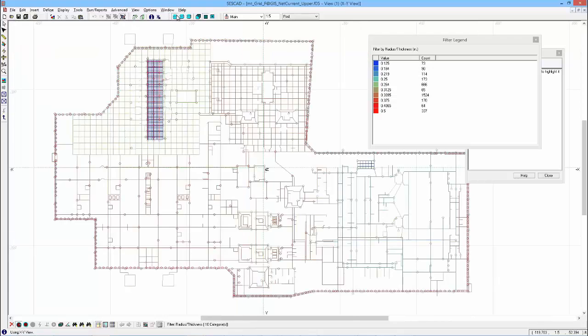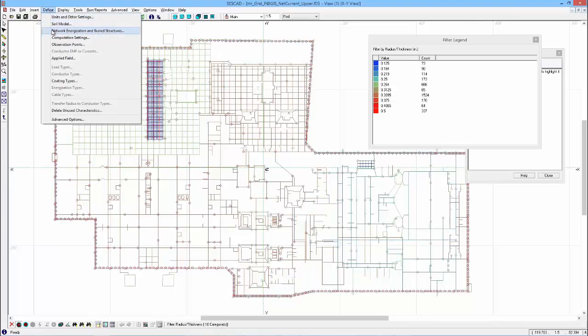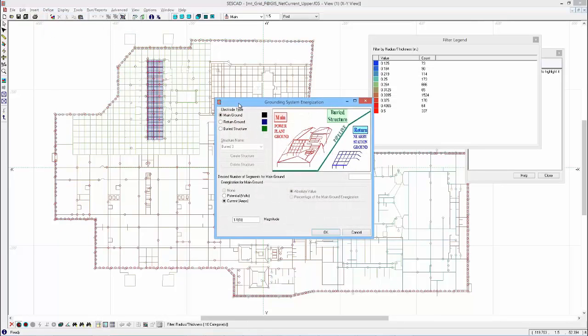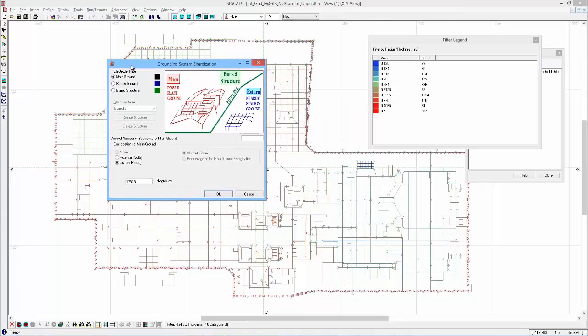Returning to our top view, the energization is specified globally for the main electrode, since we don't specify a specific fault location. Notice that there's no angle specified on the fault current because, again, these are like superconductors energized in DC. There's no point in specifying an angle, nor is there a frequency specified. The program won't be using that information anyway.